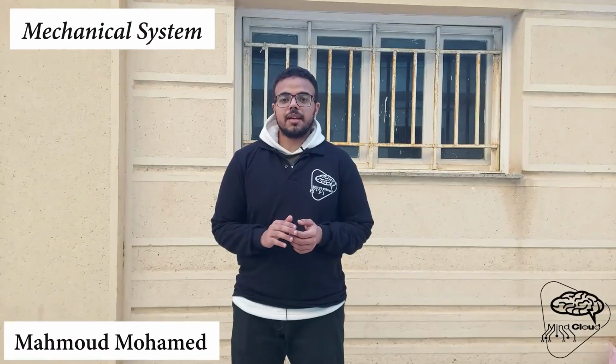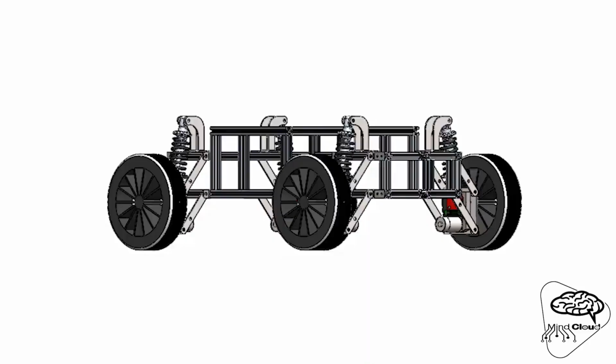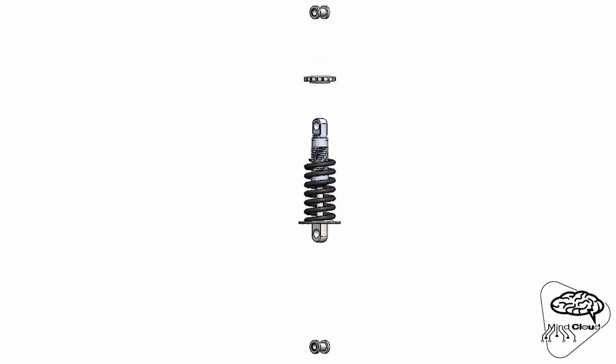I am Mahmoud from the mechanical team. We selected 4-wheel skid steering mechanism to design our rover. We designed a motor bracket to place the motor in to secure it from shocks. Our motor has 380 kg/cm torque. The suspension system in the rover is similar to that one in the cycle, which absorbs vibration.